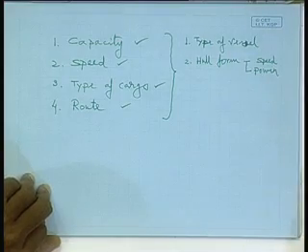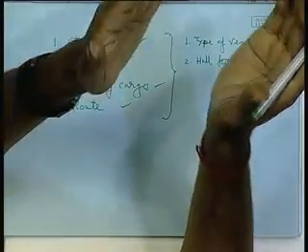If you come out with a hull form, and he comes out with a different hull form, and both are giving the required speed, say a speed of 15 knots you have asked for as the customer, and you are giving it at the expense of a 10,000 bhp motor, and he is giving it at the expense of an 8,000 bhp motor, definitely his is better. If you install higher power, your specific fuel consumption is more, and operational cost will be more. So, power, what else?